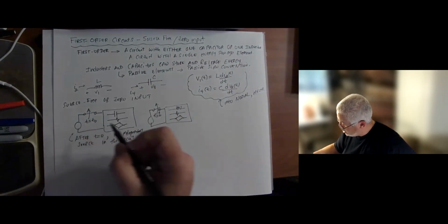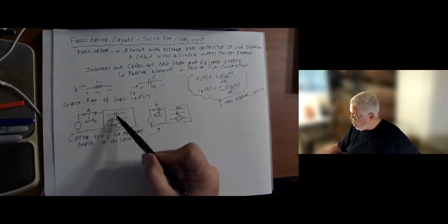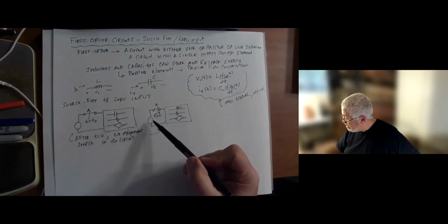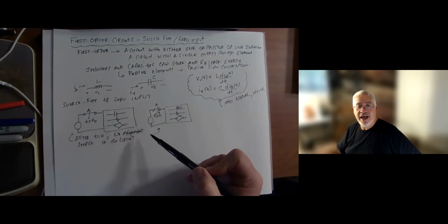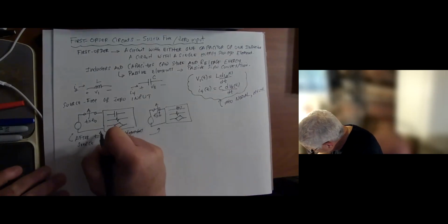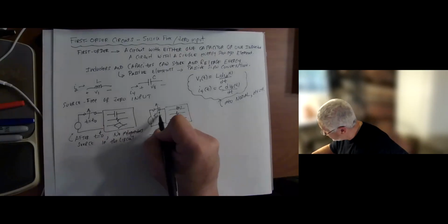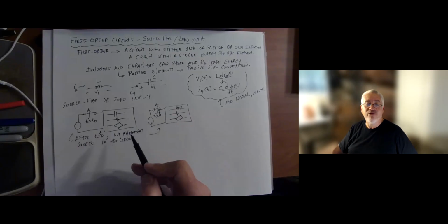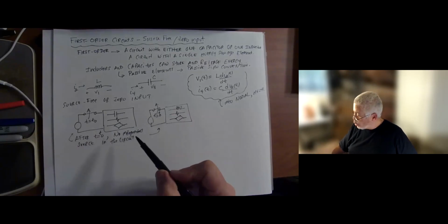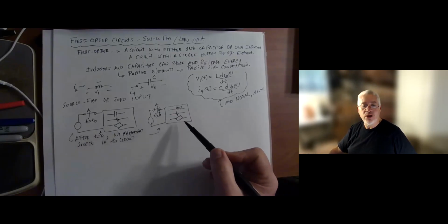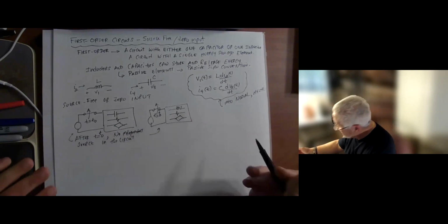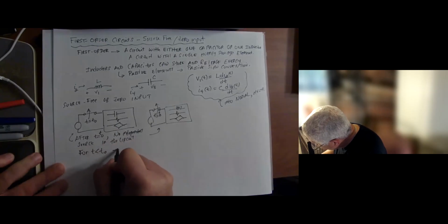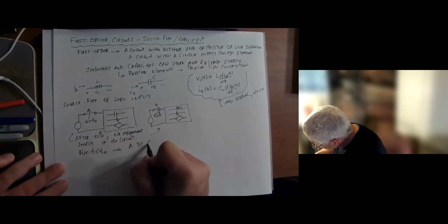Either for here or for here, we're looking at a first order circuit, either one capacitor with resistors and dependent sources, or one inductor. And then the independent source gets disconnected at some time T naught, that is, after T equals T naught. Could be 0, but it could be another time. Just to be generic, I'll put T naught here. After that, essentially, the circuit has no independent sources.